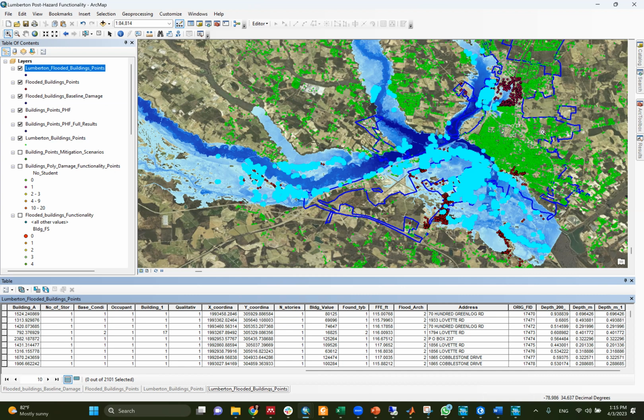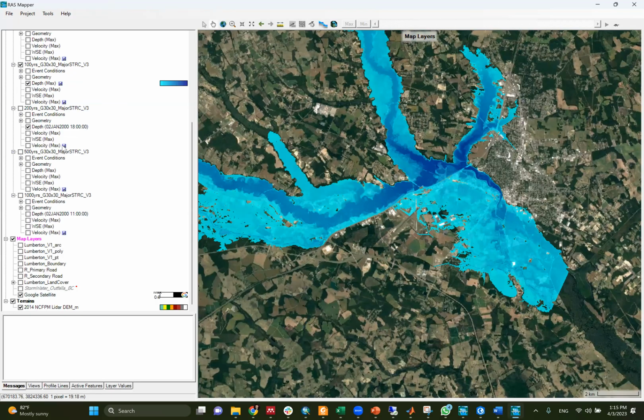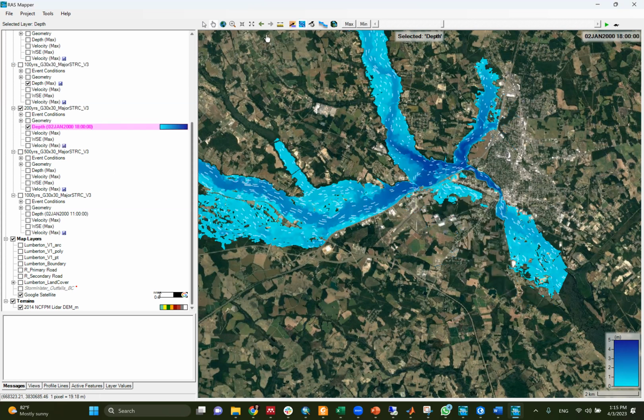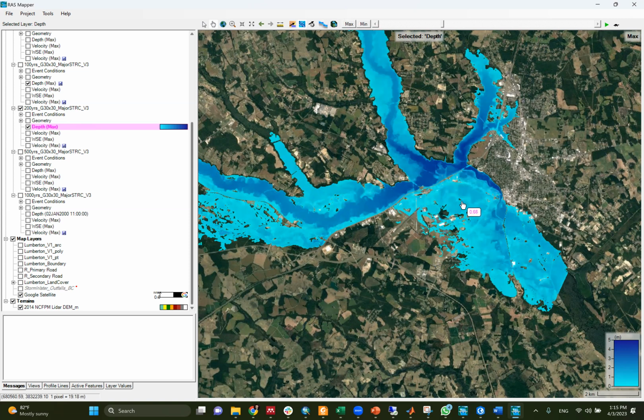So we do our calculation not based on the ground elevation. But when you export this hazard map from HEC-RAS, if I click here, all these values, like this maximum, like 0.2, 0.49, 1, are measured from the terrain, the digital elevation map, which is the ground elevation. But what I'm interested in is the flood depths measured from the first-floor elevation.